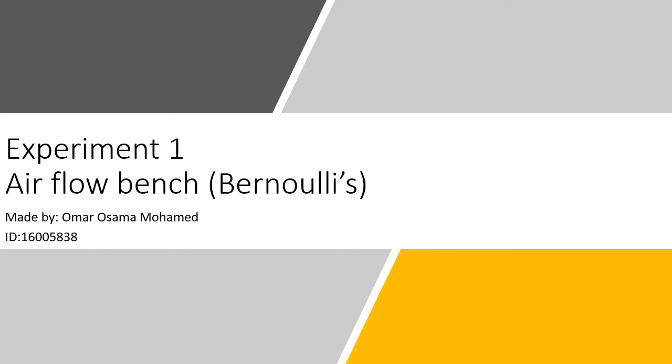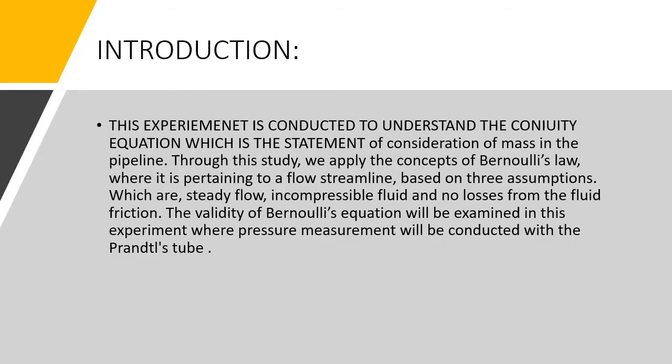I'll be presenting about airflow bench, Bernoulli's equation. Introduction. This experiment is conducted to understand the continuity equation, which is the statement of conservation of mass in the pipeline. Through this study, we apply the concepts of Bernoulli's law, where it is pertaining to a flow streamline based on three assumptions, which are steady flow, incompressible fluid, and no losses from fluid friction. The validity of Bernoulli's equation will be examined in this experiment, where pressure measurement will be conducted with the Prandtl tube.